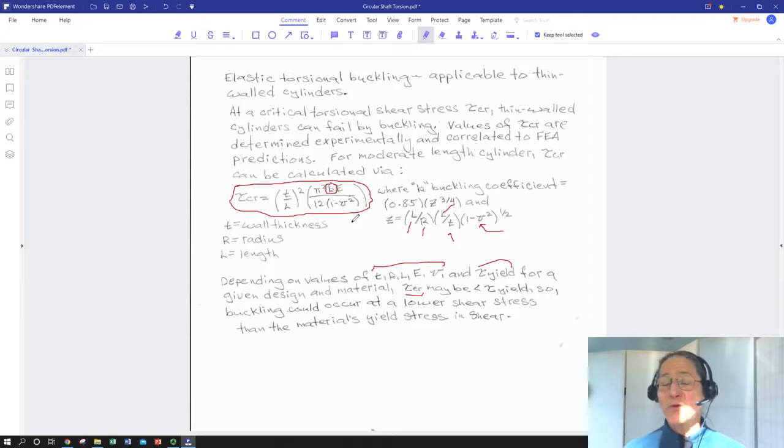So that is it for our torsional circular shafts lecture series. We have restricted ourselves to circular cross sections just because it makes the integration easier of the relationship between moments of inertia and things like max stress. You can take the same argument and apply it to any cross-sectional shape. You would just need to use expressions that relate any time you're relating radius and you're calculating areas and volumes. You'd need to use appropriate geometric expressions to get material at a given distance from your radius for that shape. So you can use an ellipse or a square cross section.